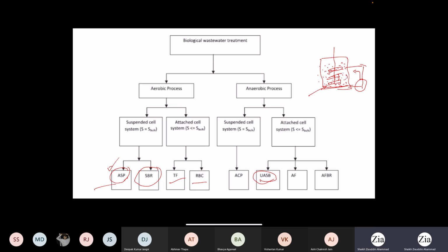These are the common methods used to keep the solid suspended in the liquid. So wherever you use aerobic treatment system, you can use aeration. You can use air or oxygen. Commonly we use air to keep them suspended. Or you can use a surface agitator, a mechanical surface agitator. This surface agitator is actually similar to an impeller or stirrer.